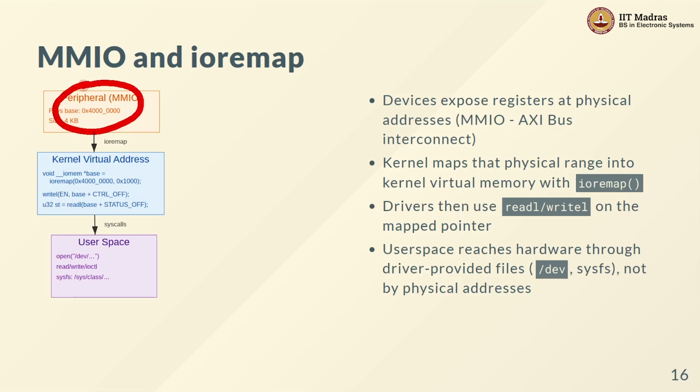I have got a peripheral. Let's stick with our smart timer, right? So what does a smart timer peripheral look like? It has a certain set of addresses associated with it. Well, in this case, I've mentioned the 4 KB address space. The smart timer was less than that. We basically used, I think, 6 bits of address, right? So maybe just a 64 element address space, but it doesn't matter.